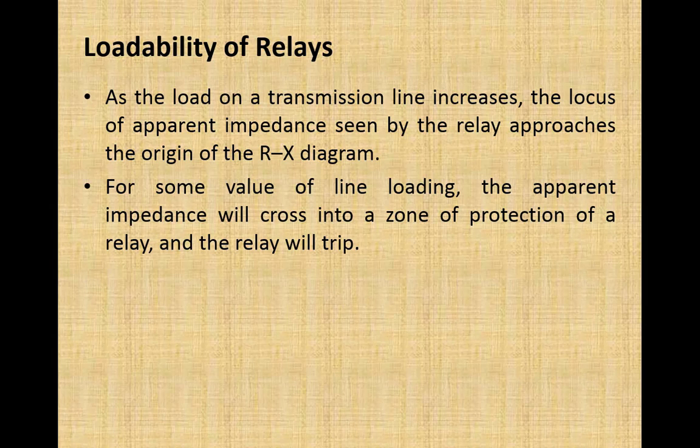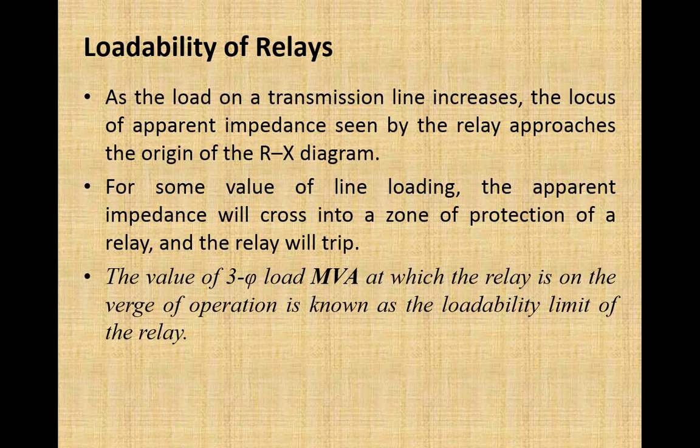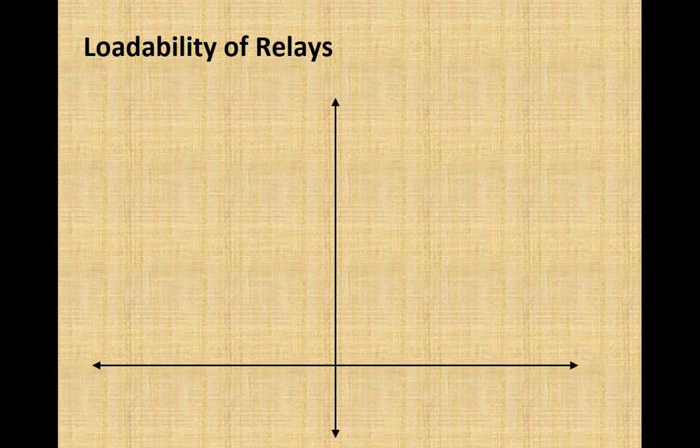So this is how we define loadability of a relay. The value of three-phase load in MVA at which the relay will be on the verge of its operation is known as loadability of a distance relay. Here we explain this concept of loadability of relays with the help of the RX diagram. Up to this point we have a lot of know-how about this RX diagram, so now we can explain this loadability concept.